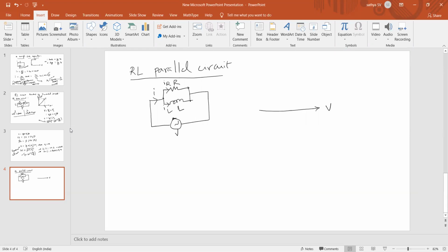Now we will move on to the individual elements. The first point is the resistor. What is the relation between V and I? In phase. Right. Don't look at the circuit and confuse yourself, just answer my questions. So V and I should be in phase. That means IR and V are both in phase, and the angle of difference is 0.